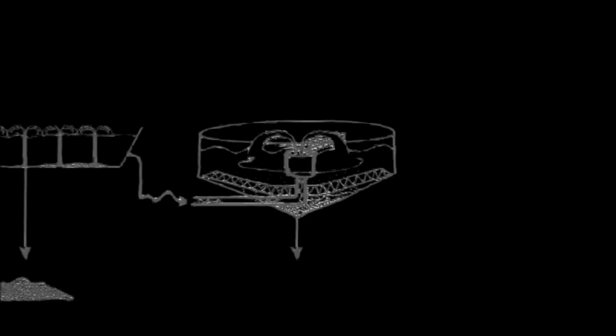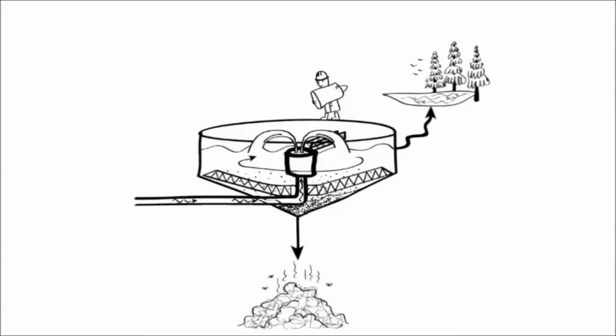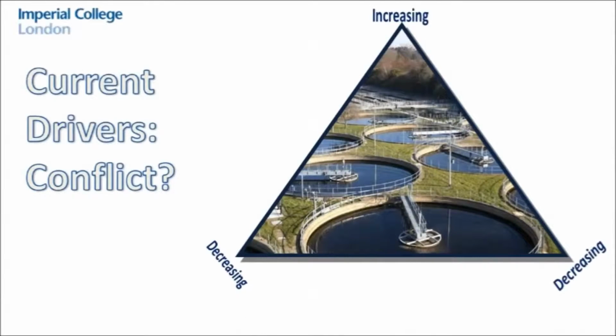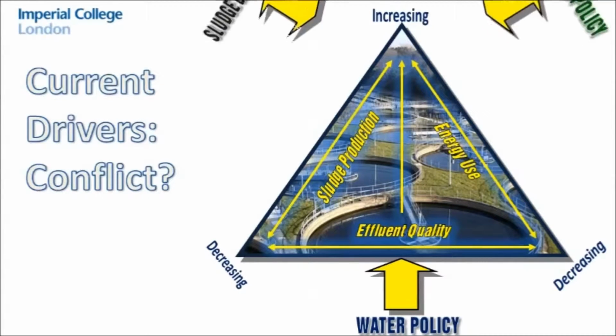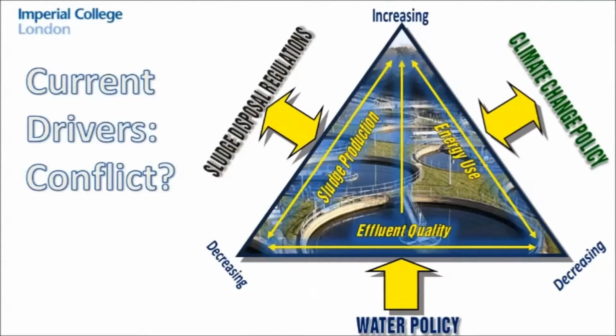There are tertiary treatments that can also be applied to further reduce BOD and TSS. However, they carry with them the potential for environmental trade-offs that may not justify the additional improvement in effluent quality. Consideration of the cost-effectiveness of alternative treatment practices, as well as a balancing of numerous engineering factors and non-water quality related environmental effects, including energy trade-offs, weighed against additional incremental improvement in effluent quality.